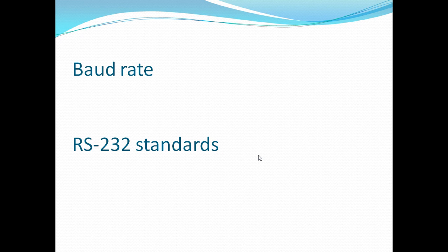Total 10 bits of data is transferred for one particular character or data type. So we are encoding this 8-bit data into 10 bits with one start bit, one stop bit, and 8 bits of data. After transmission of the start bit, LSB is always sent first and then MSB, and after that the stop bit is always sent in 10-bit manner.